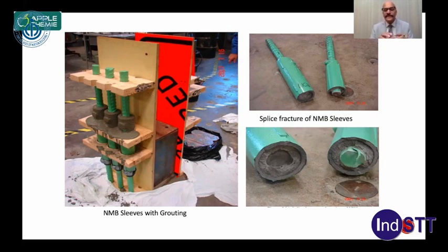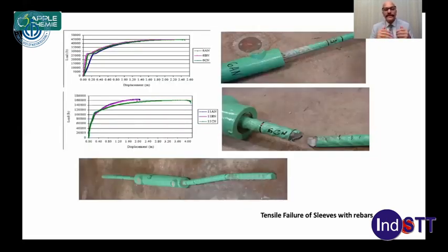This is what I mean. The grout around the rebar should be absolutely full and total. So that shows a full grip. If you cut the splice, this is to be done mechanically by force. And the other part of testing the grout is you can put it into the testing machine for tensile failure. If you go in for the tensile failure, the failure should be in the parent material. Obviously, it should be in the rebar and not in the coupler section. So this coupler section should remain intact and the failure should come here or here, whatever it may be.